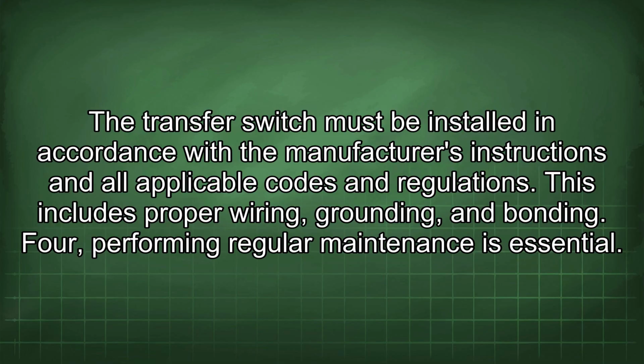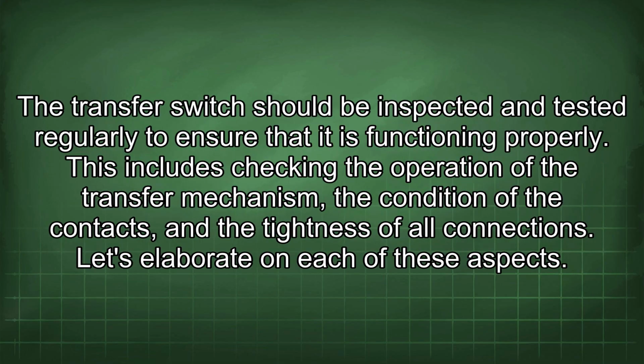4. Performing regular maintenance is essential. The transfer switch should be inspected and tested regularly to ensure that it is functioning properly. This includes checking the operation of the transfer mechanism, the condition of the contacts, and the tightness of all connections. Let's elaborate on each of these aspects.